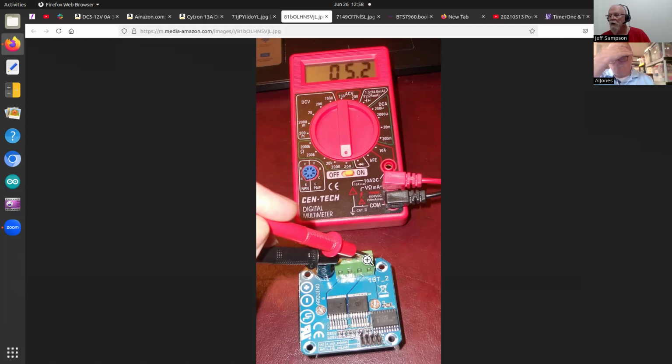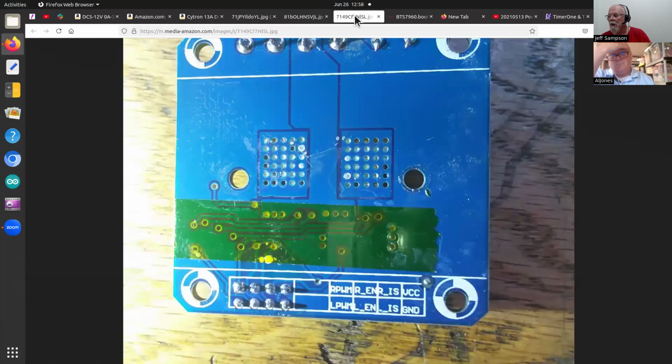And he tracked it down to the fact that he claims that it's because, I don't have that picture, I don't think. He claims that when this heatsink is bolted on, there's no insulation between all these open vias and the back of the heatsink. And the reasoning is usually that people will say, well, I've got a heatsink that's anodized aluminum, and the anodizing insulates it to some degree. But he's claiming when he looked at the back of the heatsink, he could see holes in it. So something they tightened it down against here had broken through the anodizing and caused a problem.